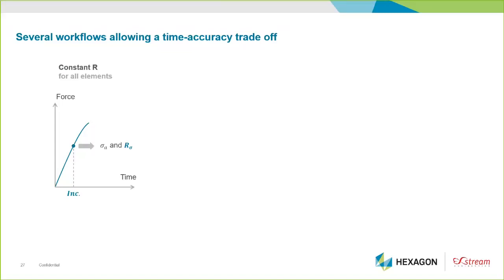As Lucien mentioned previously, it's really an approximation, because he illustrated that load ratio is varying over the part and with load amplitude. So applying a load ratio of -1, whatever the element and whatever the load amplitude, is a big approximation. It can work as a first start, but then you may need to go for something else.